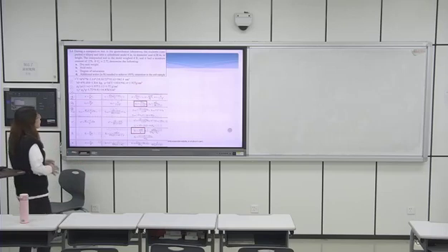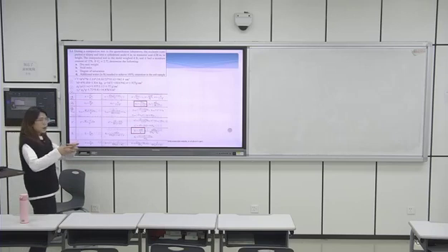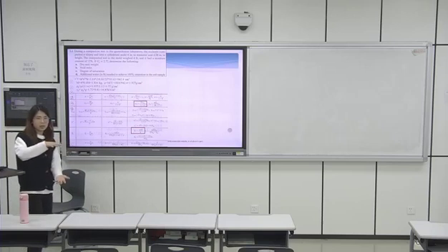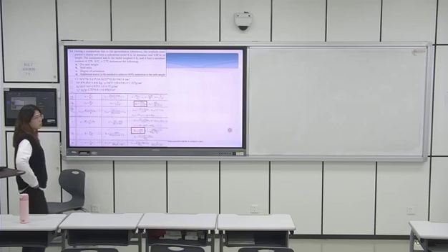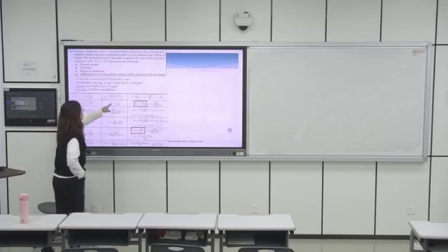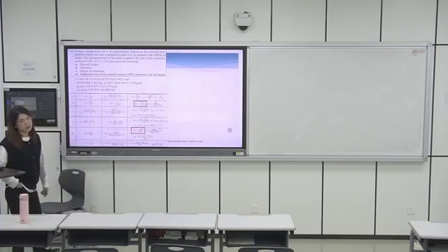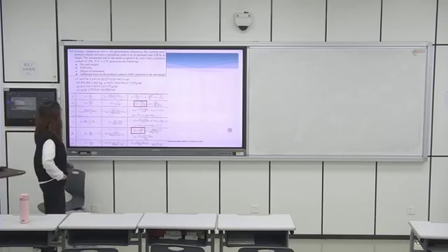You need to calculate it with the size of the mold. It is a cylindrical mold. It gives you diameter and height. Then you can calculate the volume, right? So first, calculate the volume, and with the weight of the soil, then you can calculate the moist unit weight. And then with this equation, we know the water content, then you can calculate dry unit weight.